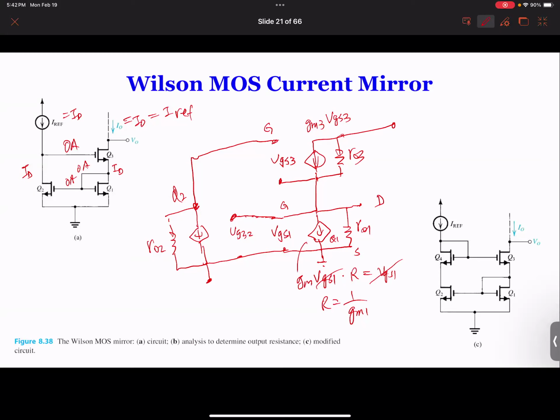So you see, now you have two resistances in parallel. In the BJT case, you have more resistances in parallel, but now you have only two, so a little easier. Here is the same, but the other one is not connected. You see, the circuit over here is standalone, right? It has nothing connected because the top one is open. The one we leave with the VGS, like a terminal over there, is only to calculate VGS3.